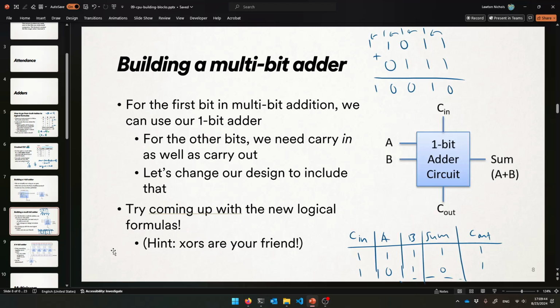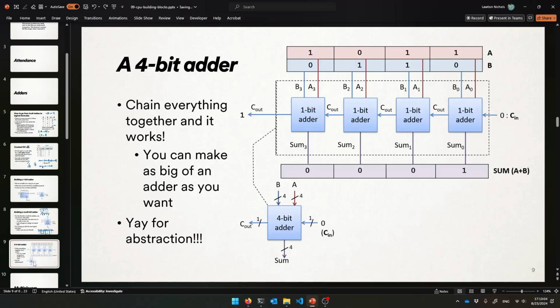Okay, so let's take these adders that have carry-ins as well as the bits, a sum and a carry-out, and chain them together, because that's all we need. If we just chain the carry out of the previous one into the carry in of the next one, do you see how that'll give us what we want? So here's my 4-bit adder. Let's add 4-bit numbers together. Here are my two numbers that I want to add, each of their bits hooked into the adders, like a 4-bit register. And our initial carry-in to the first adder is 0, because there's no carry-in to the first thing.